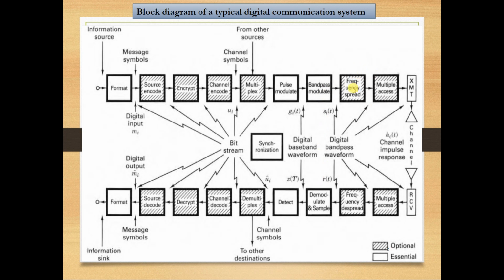So we now understand the frequency spread. There are two types of frequency spread. There is CDMA, code division multiple access spread, where you multiply by a code, and there is frequency hopping spread, where you keep jumping your signal from one frequency to another in order to spread your interference and make sure that if there is an interference source, this interference source doesn't kill your message.